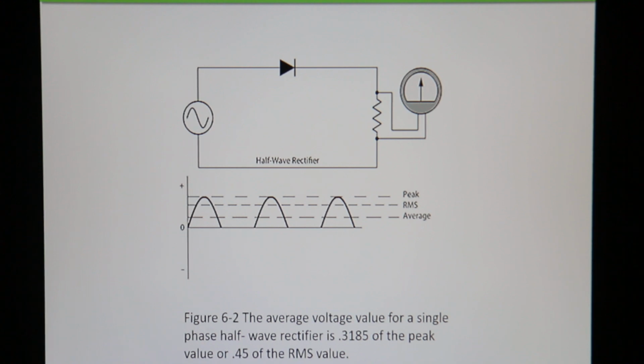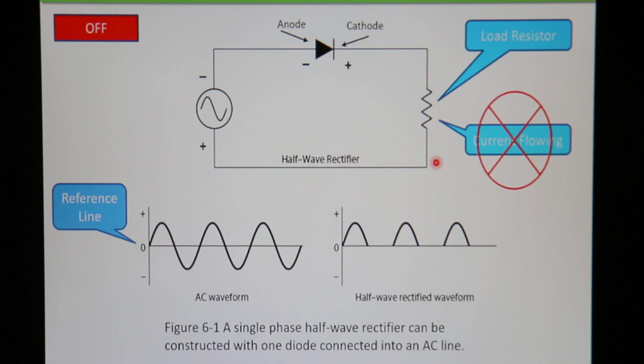Remember, AC voltage is always changing. DC voltage or DC current is always constant. So when you look at power, AC is moving all the time. It's always changing. It's always going back to the 0 point. So we have to have some way of trying to quantify what effective voltage we have out of it. Okay? So when we're in AC, I'm going to flip back here. When we're in AC here, we talk about peak, and then we talk about the RMS value.